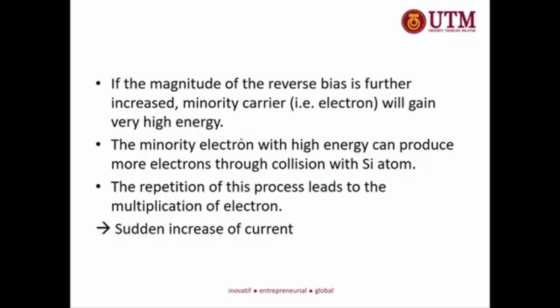With such energy, the electron can produce more electrons. So a minority electron with high energy can produce more electrons through a collision process with the silicon atom.